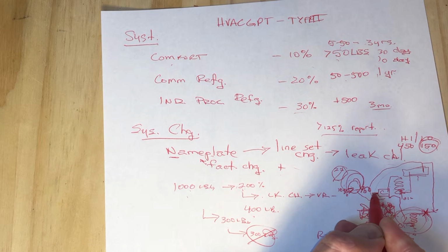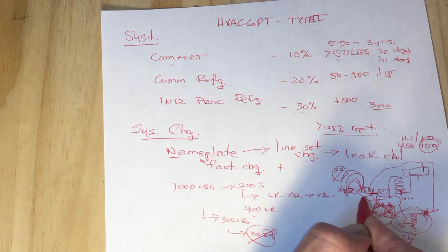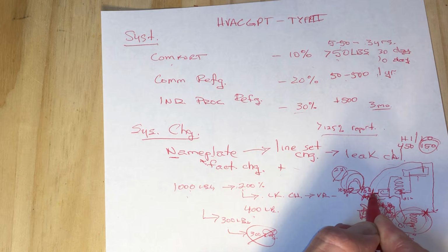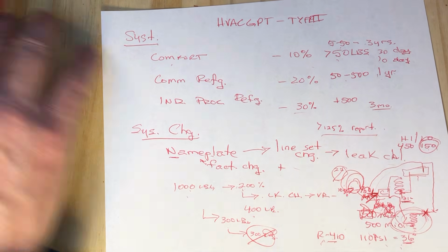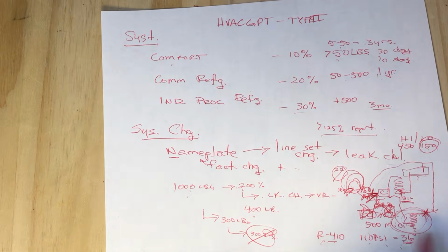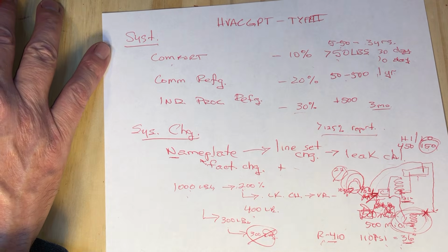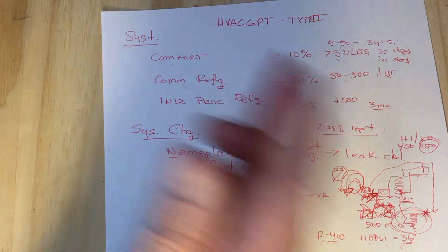And then sometimes the rotating shaft seal, sometimes it's an open drive compressor that has a motor connected to it, and the shaft seal right here will also have traces of oil, and that, if it sits in mothballs for a long period of time, could cause that as well. And mothballing, again, is when they're isolating.